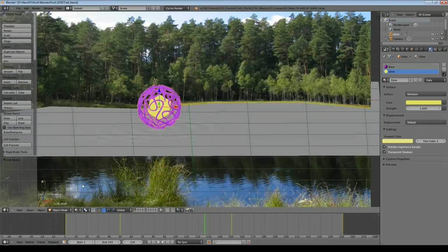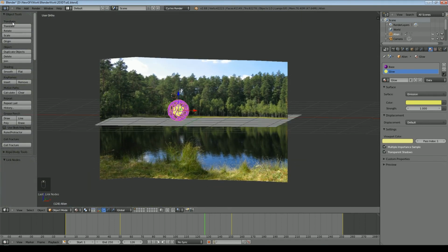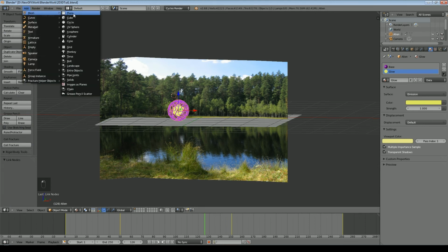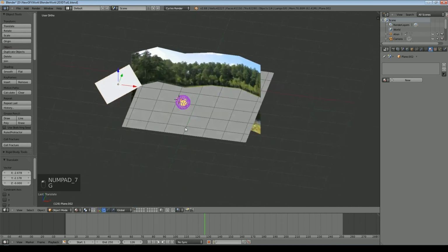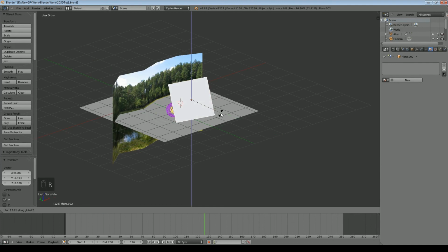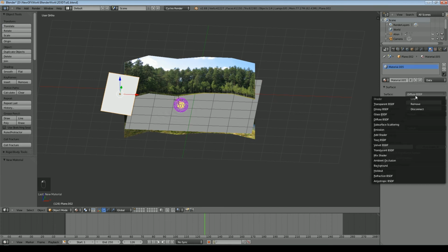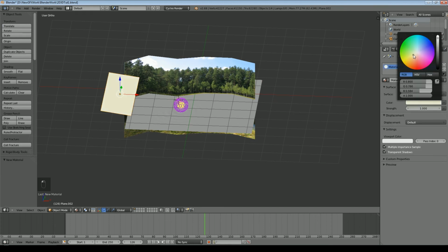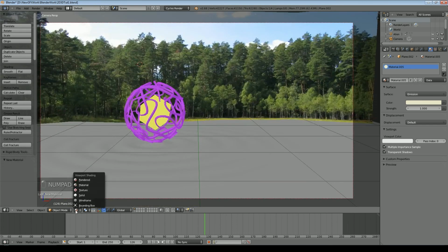So if we go to material, we can really see there's shadows on this grass down here, so the sun is up and to the left slightly, perhaps behind the camera. So I'll add a plane, we'll lift that up, we'll rotate it a little bit, rotate on the Z, bring it over here somewhat, rotate again. Strictly speaking, you should probably use spheres, but generally it doesn't matter too much unless you've got really sharp reflections. We then put a material on that which is an emission, give it a yellow color because it is supposed to be a sun, and then we'll go to the camera and rendered mode with the lamp still selected.